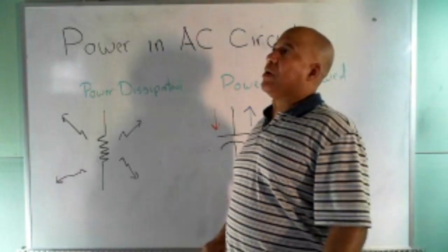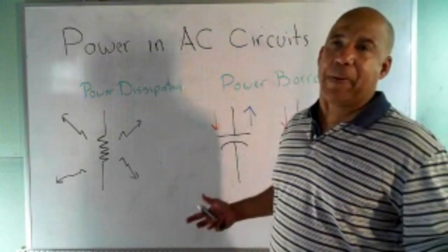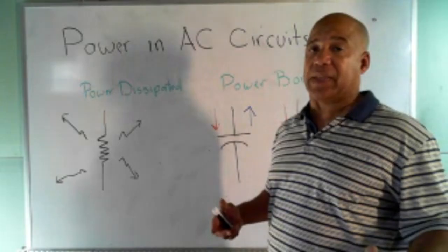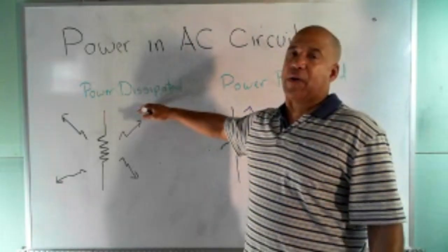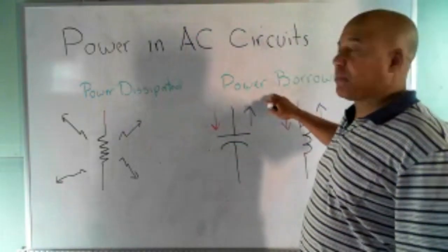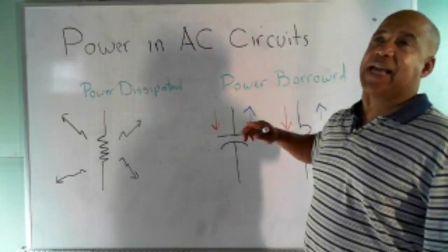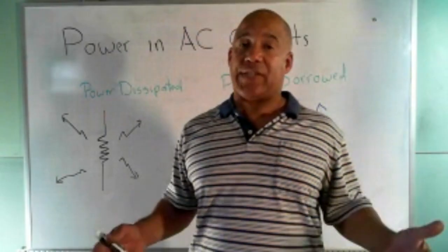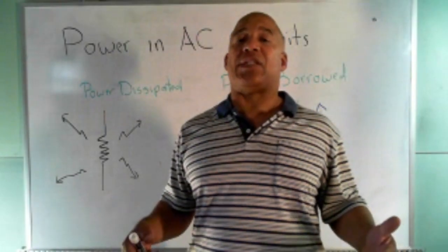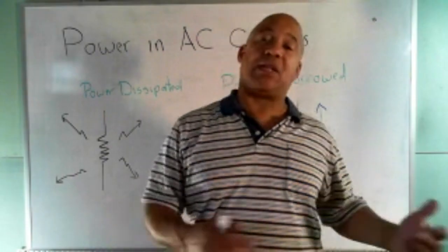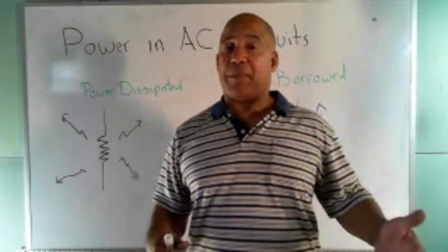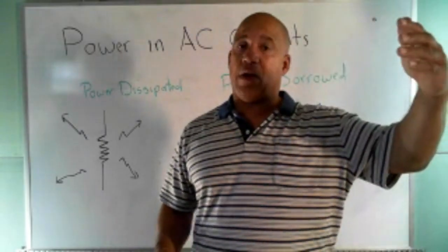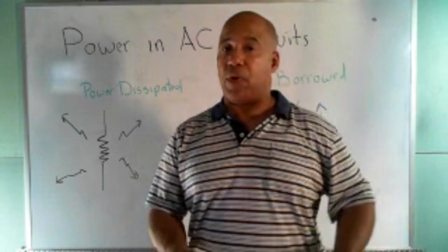And so if there's a good power and a bad power, it really depends on what I'm doing. But if I want something to happen, if I want work to be done, then we will consider resistive power the good power and reactive power the bad power. Now, having said that, we have a measure of how resistive or reactive the power is in the circuit, and that's given by something called the power factor. And I kind of touched on that a couple classes ago, that looking at the power factor, you can tell if the circuit is resistive, if it's reactive, or if it's somewhere in between.